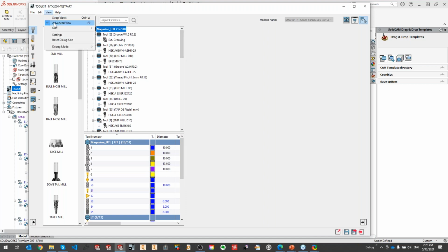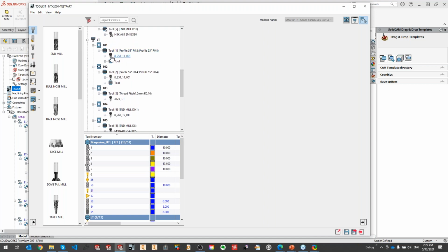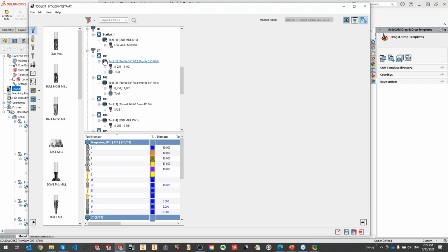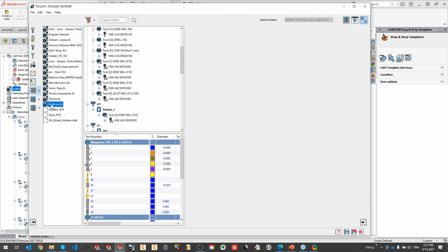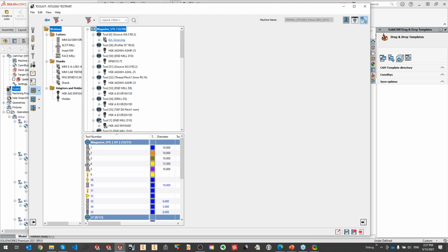And if you're not using the advanced view, then you always need to start from the cutter itself and go towards the holder. So I'm always using the advanced view, not only because of what I just mentioned, but I really like to see every single station, view and those kinds of things. Everything looks more organized to me, mostly for mill-turn and Swiss-type machines. I always prefer to have this view for those kinematics. Right, so I will be using this on the upper turret, but it doesn't matter. I can just put it anywhere in the tool magazine.